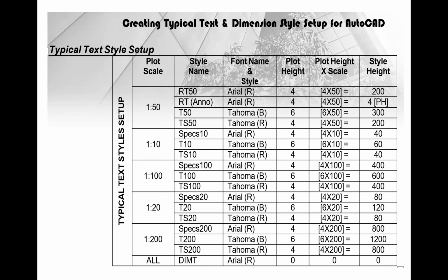The real issue is when you give it a height of 0, later on you will be able to manipulate the height and change it to what you want. When you give it a height of 4 or 6 or whatever else, when it's time to use it, it is going to already have the height, so you won't be able to change it depending on what you're doing. So that is the distinction. When you make it 0, then later on, when it's time for you to use it, you have the flexibility to change the height. It's just that when you make it 0, the software is going to force it to be 2.5. I guess Autodesk is saying that the smallest you want to make your height on paper is 2.5, because anything smaller than that, nobody will be able to read it.